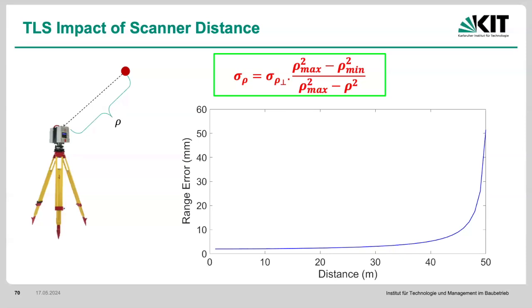You don't need more than that. You have to add more scans to be able to get it, especially for quality control. For progress reporting or for just object detection, that could be sufficient, 40 meters even. But if you want to do quality control, 20 meters is where I would basically draw the line, okay?